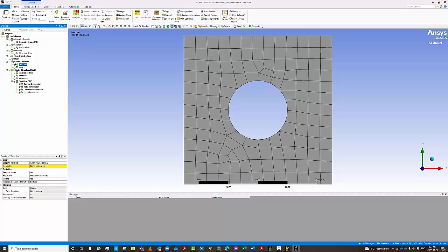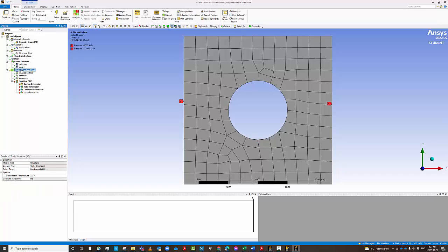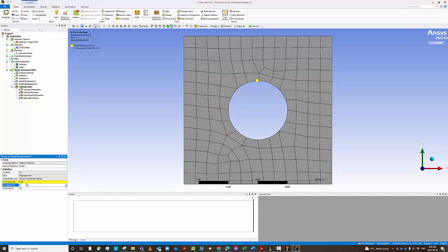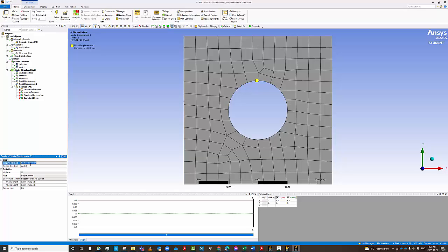Okay, now we go to this one, named selection, and I'm going to go here again for node and pick this node. And I'm going to apply. Node number 2, excellent. Okay, things are brightening up. Insert nodal displacement, named selection, node number 1. And if I go to definition here, it's going to be 0, and it's going to be 0. Right? And enter. Zero.